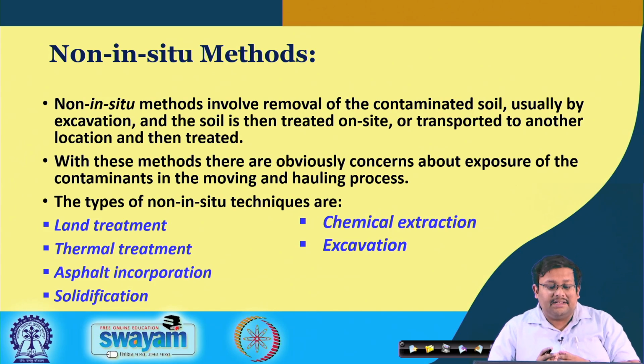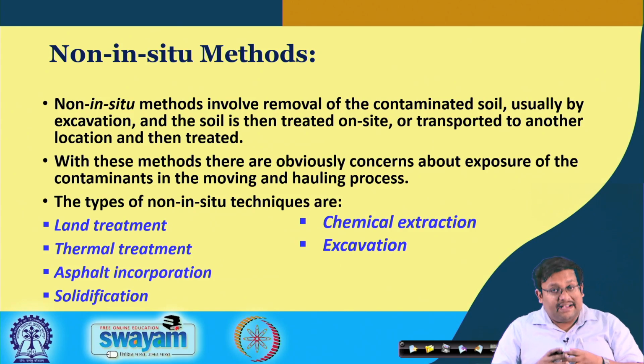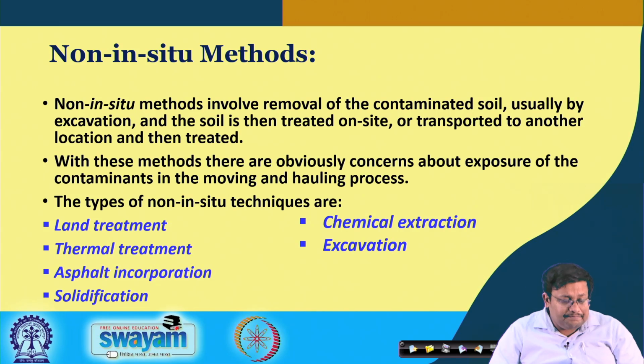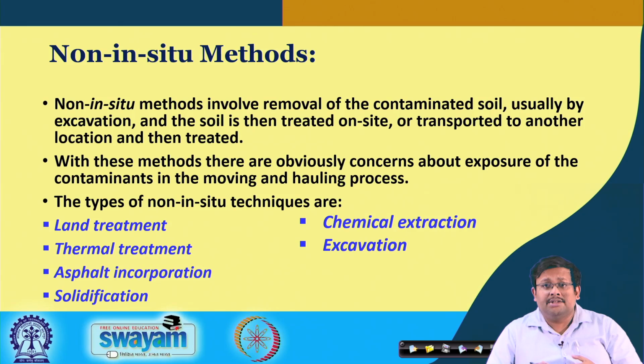Non in situ methods involve removal of the contaminated soils, usually by excavation, and then the soil is treated on site or transported to another location and then treated. So, basically it is excavation followed by different types of treatment of the soil. With this method there are obviously concerns about the exposure of the contaminants in the moving or hauling process. However, in some areas this technique is still followed. There are several types of non in situ techniques.